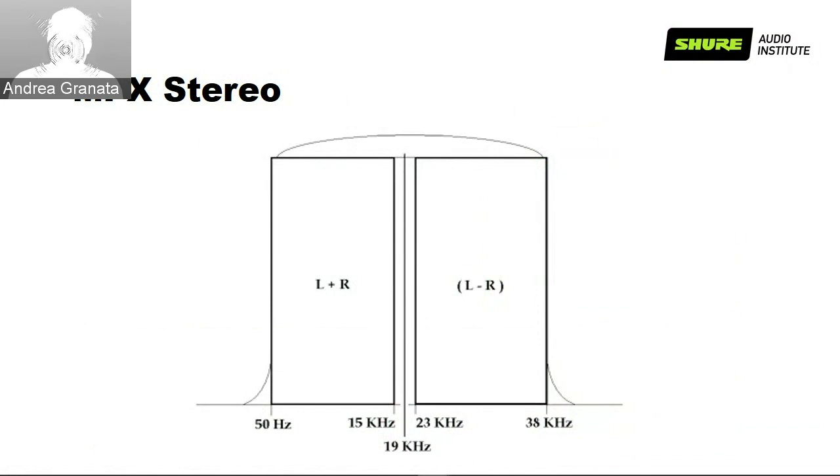Stereo multiplex transmission is exactly the same for any stereo in-ear monitor in the world, and it has a limitation in terms of frequency response. The frequency response of multiplex stereo, to be approved by the FCC and legally sold, has to be limited between 50 Hz and 15 kHz.